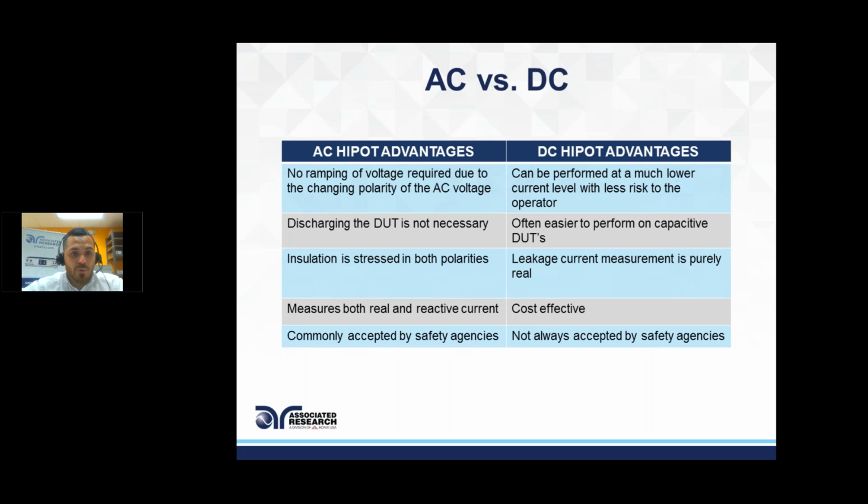You can measure both the real and reactive current. Maybe you don't know the capacitive nature of your product. Running an AC Hipot test will give you some insight into how that reacts. It's also commonly accepted by safety agencies. For the most part, AC is the first go-to.